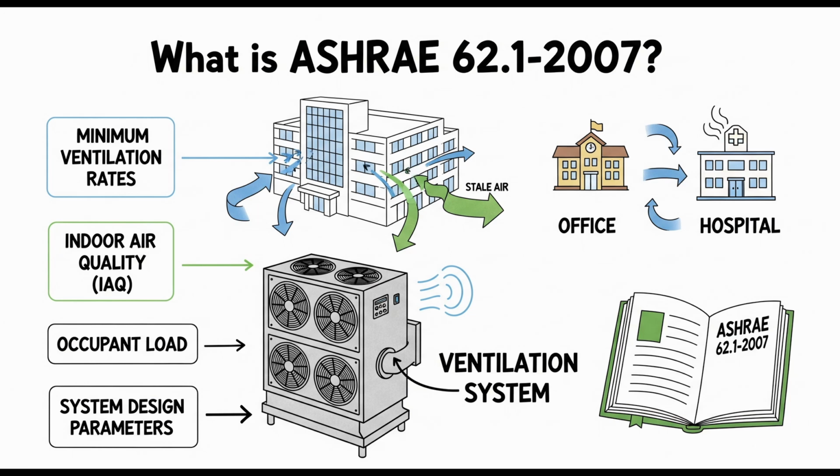But it stresses, and this is important, those subjective tests only capture things like odor or sensory irritation. They won't tell you if there's odorless carbon monoxide or radon present. You still need objective measurements for health hazards.